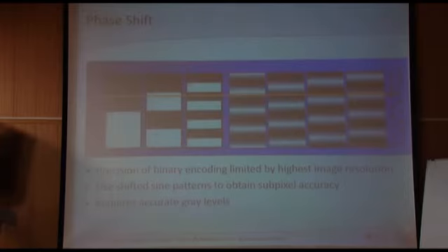The solution is not to project a rectangular signal, but the sinus signal. You see here you have a high value of the light stripe, a low value of the light stripe, and you don't have this sharp edge here, but all different color values. This ensures that if you just shift the highlighted thing a little bit, from every value you can measure the original position of the stripe, and that's why you can also measure in sub-pixel accuracy, and you don't have this problem that you had before with light stripes.